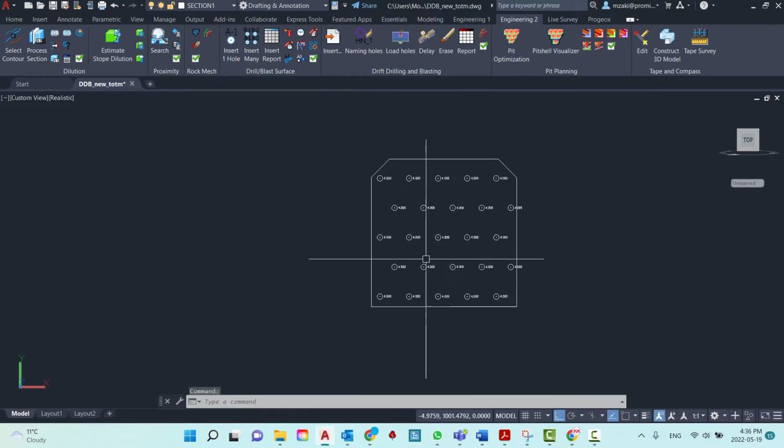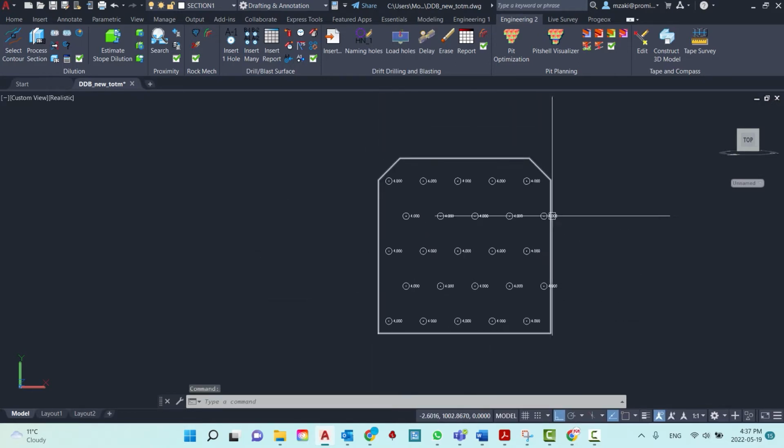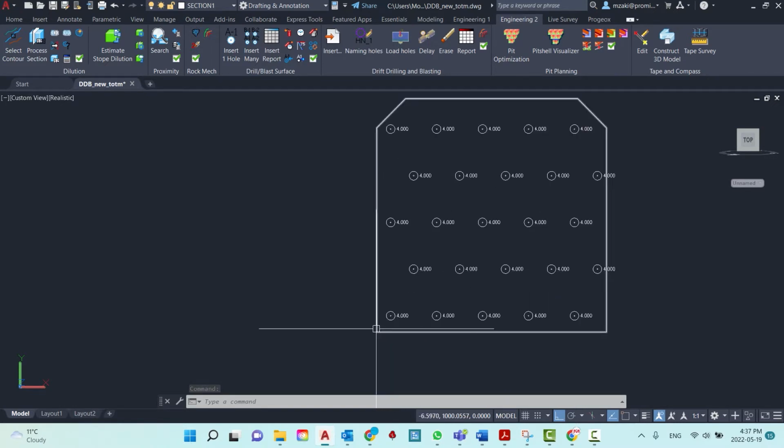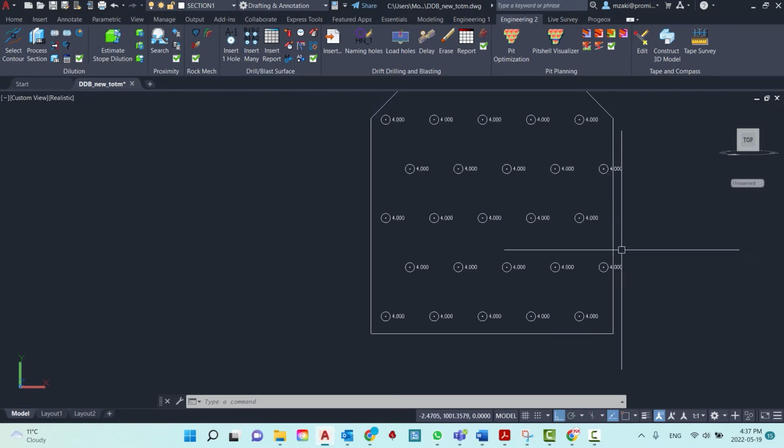So what we want to do here is apply perimeter drift drill holes. Now it's important to consider that when designing your pattern on a section, you want to make sure that the perimeter holes are always deviated away from the section. Which means that your perimeter holes will not be horizontal, but they will have either a slope or an azimuth. The reason why is because when developing a horizontal drift, you want to maintain the same surface area along the drift. So it's important to consider that each perimeter hole will have either a slope or an azimuth.